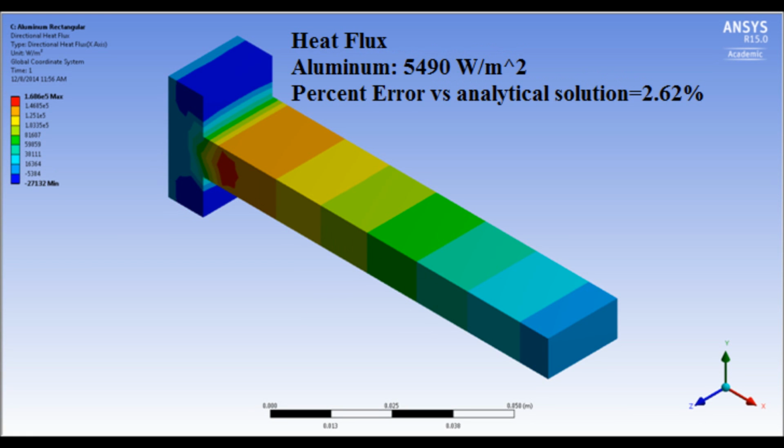We then used ANSYS Workbench to create a heat flux mesh to compute the rate of heat transfer through the fin. We also used equations from a heat transfer textbook to calculate our analytical solution for the heat transfer rate. We compared the two for each fin and recorded our percent error.